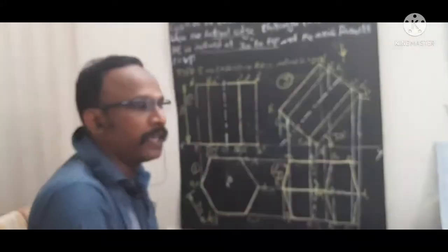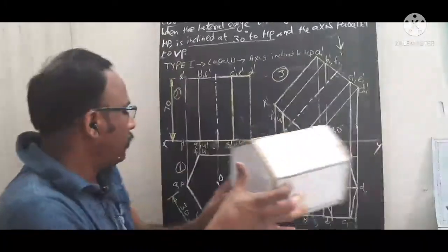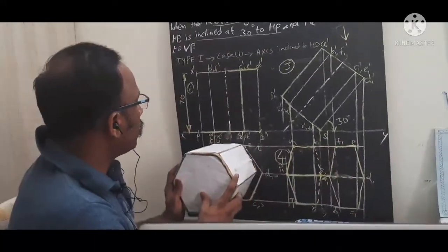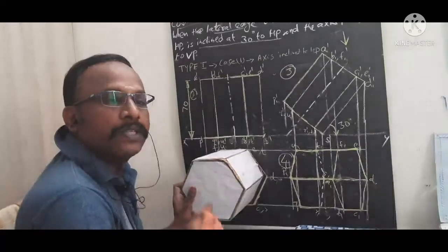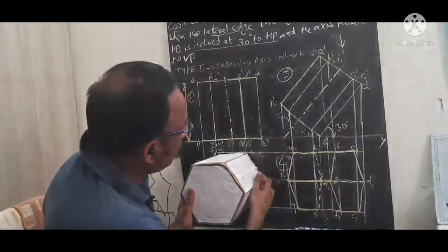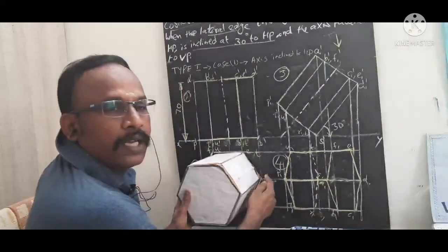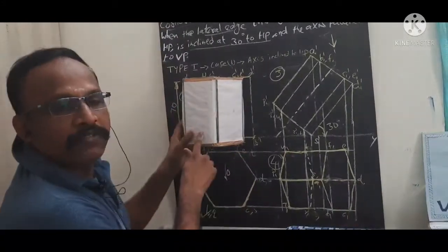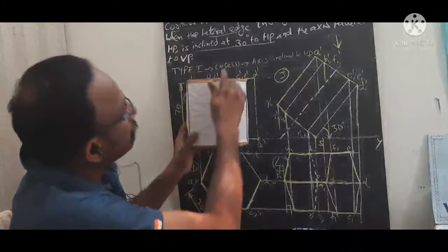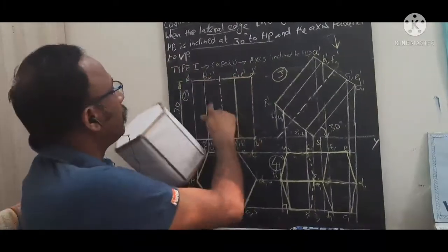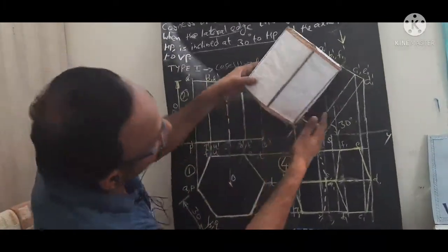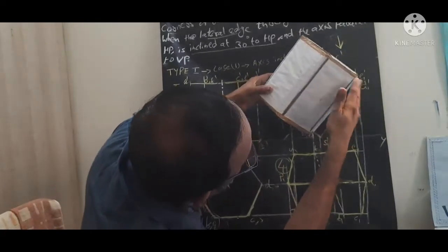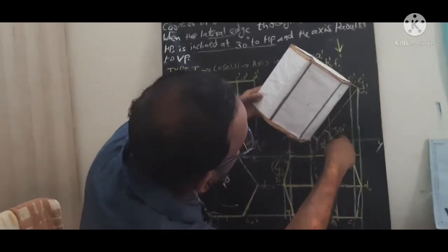So coming into the final conclusions here, first step you need to draw the front view, by keeping one of the corners on the right side. So you need to draw the front view first. Now we see these three surfaces. It will be drawn. Then we are going to tilt, for which this corner, the lateral edge, is inclined 30 degree to HV.